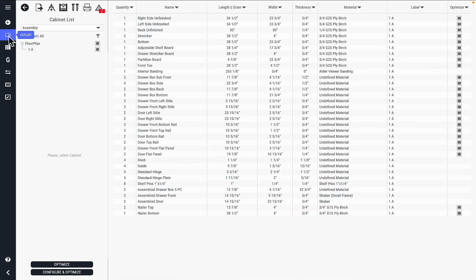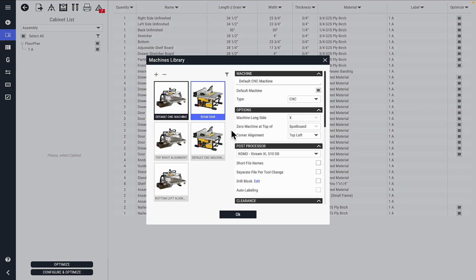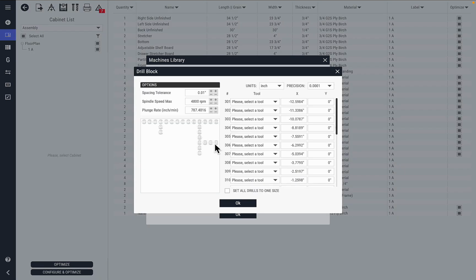2.0.0 also marks the release of drill block algorithm updates that allows us to host some otherwise irregular drill blocks that use the reference point in a way that is not aligned from the 00 drill bit. So for instance, within this Como machine, we're now able to use this column of drill bits here, as well as this secondary column that is away from the original 00 drill bit. This flexibility also opens us up for other machines that use some irregular dynamic drill bit position referencing, further enabling us to integrate with such machines.